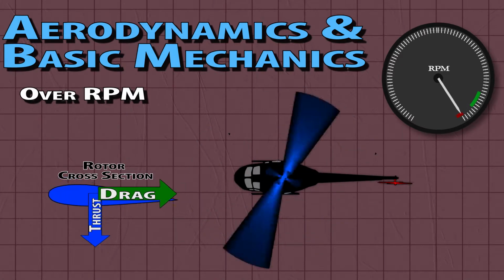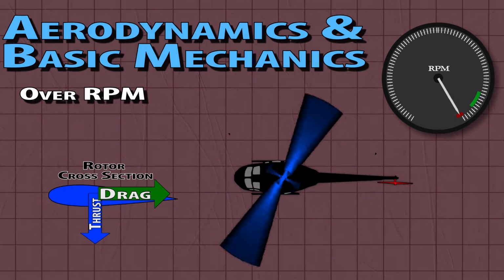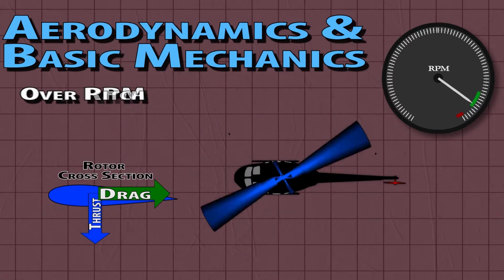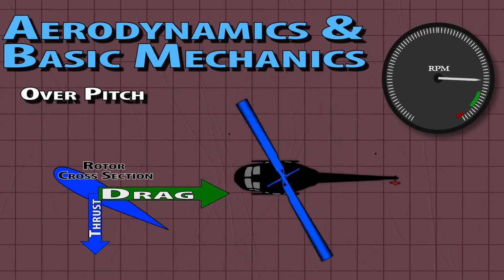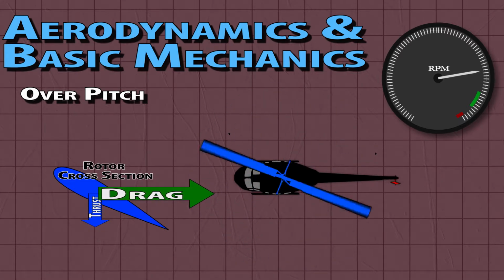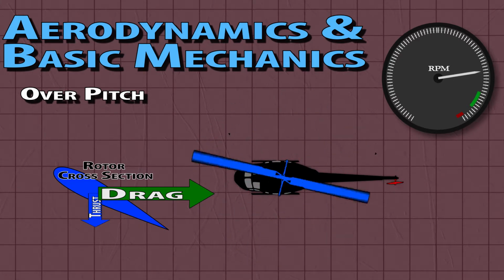However, with sudden collective dumps, in severe turbulence, or during poor auto rotations, you can cause the rotor to over RPM. Over pitch. Your helicopter has only so much power available. You can pull too much collective too fast and the blade's pitch will create too much drag for your governor to compensate. Your engine and rotor RPM will droop, your thrust will drop, and then you will drop out of the sky. The only solution is to lower the blade pitch.